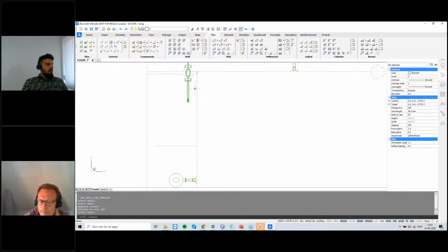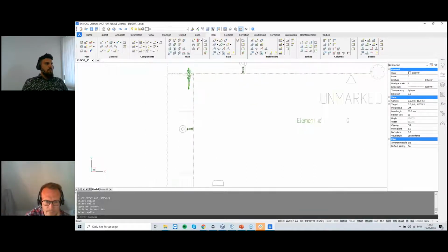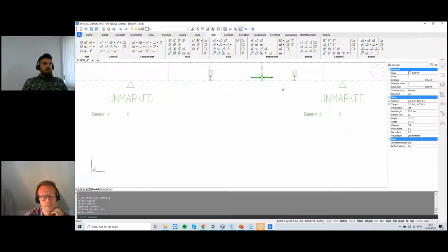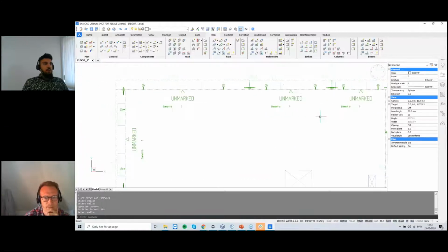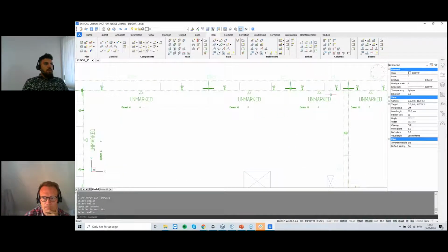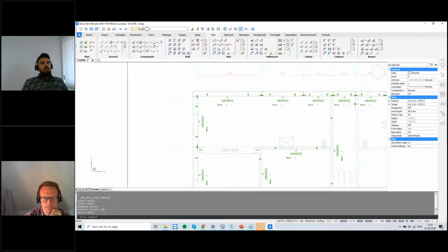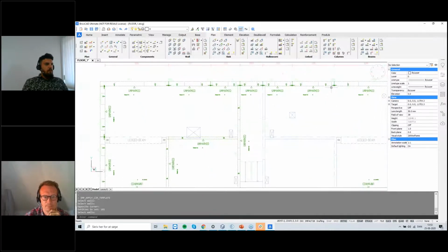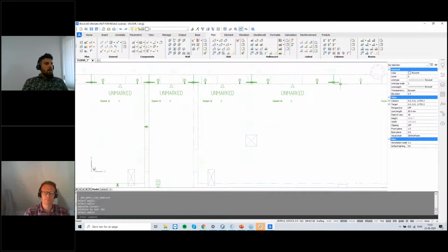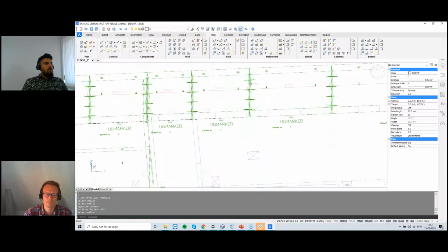So basically what I did here is add custom materials, wire loops, in this specific position, in this specific example, because these are the custom materials that we are using in Scandinavia, or at least in Denmark specifically. I know in Sweden they are using something different. And you add them like that, and then if you see, you have added them also at a specific distance from the top, a distance from the bottom, and a distance in between them.